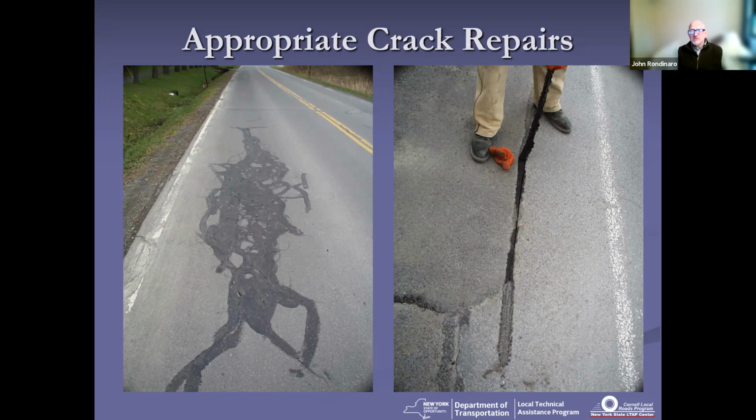In terms of the repairs themselves, you want to make sure when you're making those repairs that you've done a good job in cleaning and drying your cracks to be sealed. In this case, you're seeing that newly placed crack sealer material being pulled right out because it wasn't clean and dry. And again, that's going to raise hell with your asphalt overlay.